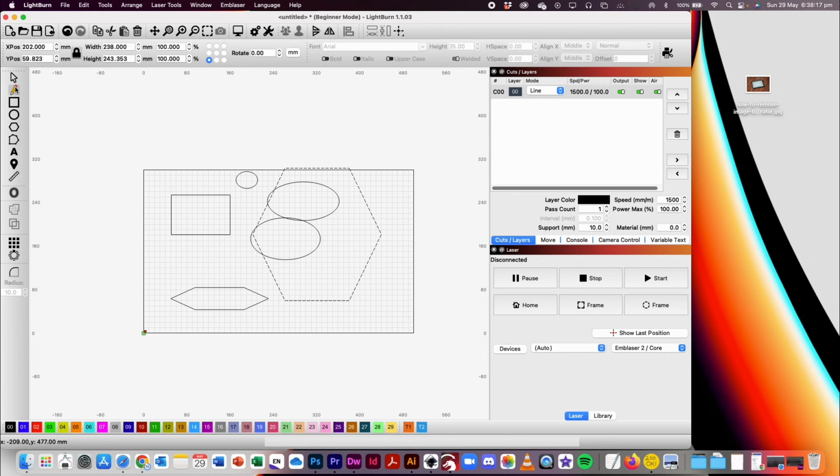And then we have our line tool at the top here, where we can click and drop, left click twice instead of clicking and holding. Clicking and holding will do a symmetrical drag of the line. If we click, hold and pull, then it can make a curved line. Alright, so that's our line tool. It will all connect together, and what you have to do is deselect the tool and then reselect it in order to start a new selection.